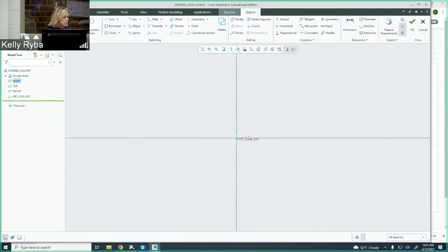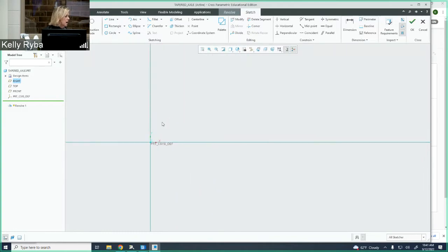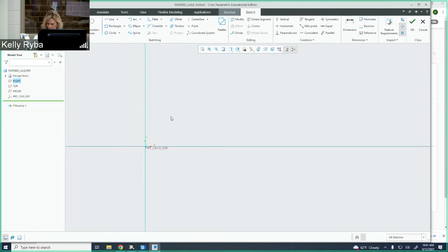Now I'm going to zoom. As we know, I think it's metric units that it kind of sets up with. So, I know that I'm going to be in English units here. So I'm going to zoom in, and I know I'm going to do a revolve. And I'm going to do it over this horizontal center line, so I need to set it up as a center line.